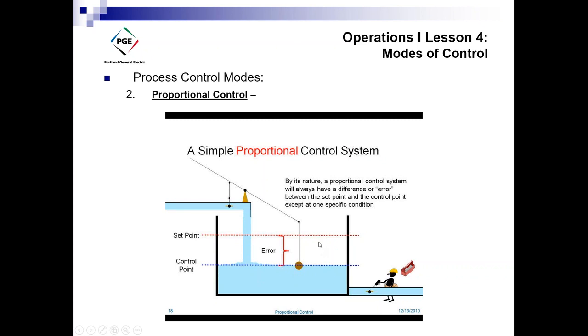Same as if you reach your set point, your level is back up, but the valve is still filling, then your proportional control does not work. Your motor control is not working. I hope that makes sense. So I want to make sure that your lower and your upper limits match the system parameters so it controls the system within the variables that it needs to.